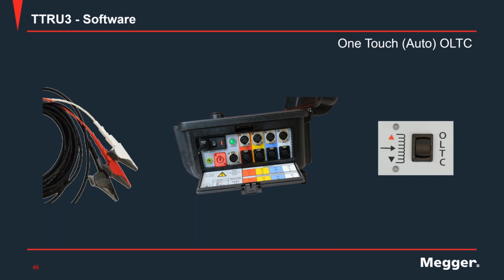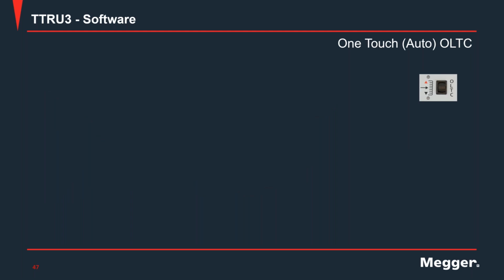Connect that to the control cabinet of your tap changer. And then on the top panel of the unit, we have the switch labeled as OLTC. As you see, you have a position to go up and a position to go down in your tap changer. So you have direct control of the tap changer from the unit. And better yet, you can obviously do those changes manually with the switch that I'm showing right now.